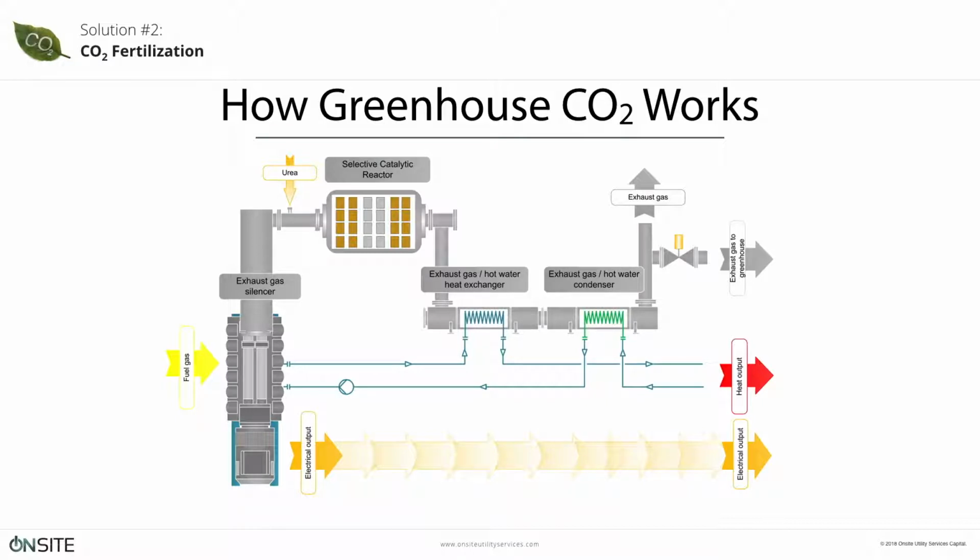consists of a comprehensive use of recovered heat used for greenhouse heating, combined with condensers applied for exhaust gases cooling to 50 to 60 degrees centigrade, all of which make it possible to achieve the total plant efficiency of 92 to 95%, while allowing to maintain high overall equipment utilization and essentially lower electricity production costs.